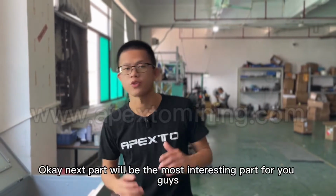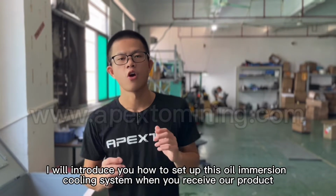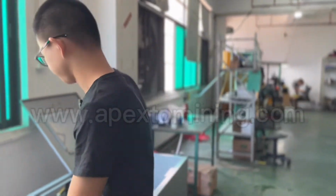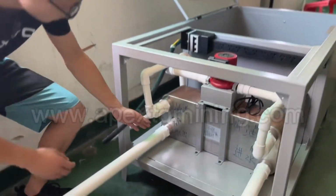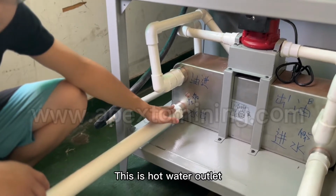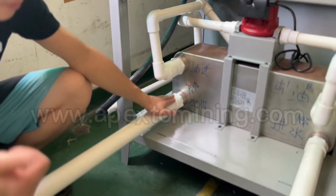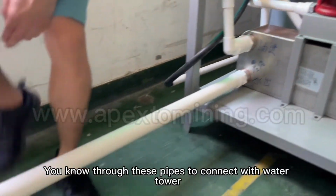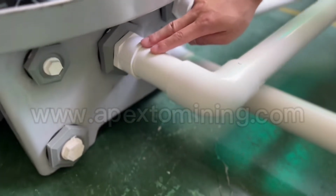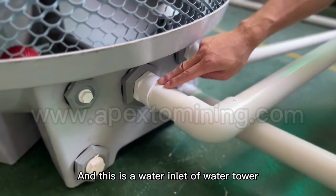Okay, next part is the most interesting part for you guys. I will introduce how to set up this oil immersion cooling system when you receive our product. Please look at this part. This is hot water outlet. You need to connect it with water tower through this pipe. And this is water inlet of water tower.